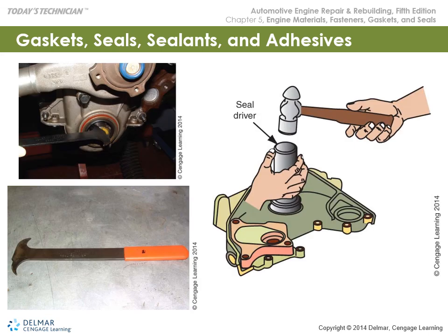How to get seals out: you have to use a driver or an arbor in certain applications, and some you can get out with the little crow hook here. I do that really carefully, so this tip is not scratching anything and it's catching inside the seal surface. So you want to be careful and pry it in at least 3 locations so you can ease it out. The last thing you want to do is damage the assembly that it's coming out of.